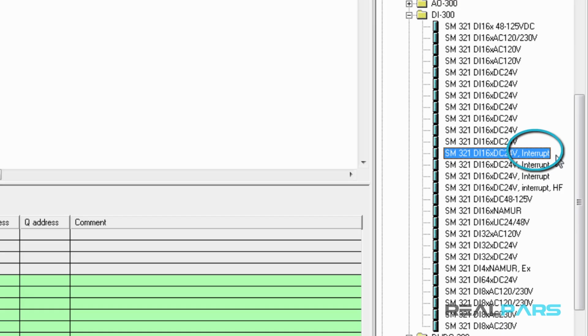For example, it activates a certain output, and depending on the activation of that output, a message appears on the HMI page and notifies us about the sensor wire disconnection. We're going to talk about how to configure these cards with interrupt abilities in the future courses in more detail.